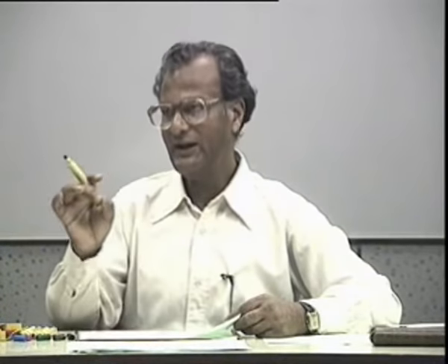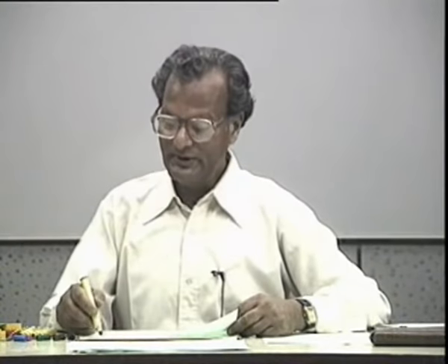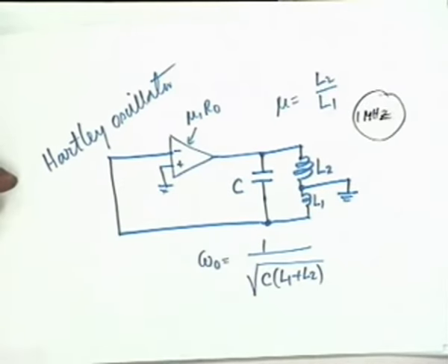You can ask, if it is shielded and sealed, how do you change the inductance? Well, there is a screw at the top which varies the length of insertion of a ferrite rod, the core inside. If it goes further inside, inductance increases. If it comes out, inductance decreases. So variable inductors, very high quality inductors are available in the market, provided the frequency is high, of the order of a megahertz or so. Okay, so on the other hand, in the Colpitts oscillator, capacitances can be made without much electrostatic coupling between them.